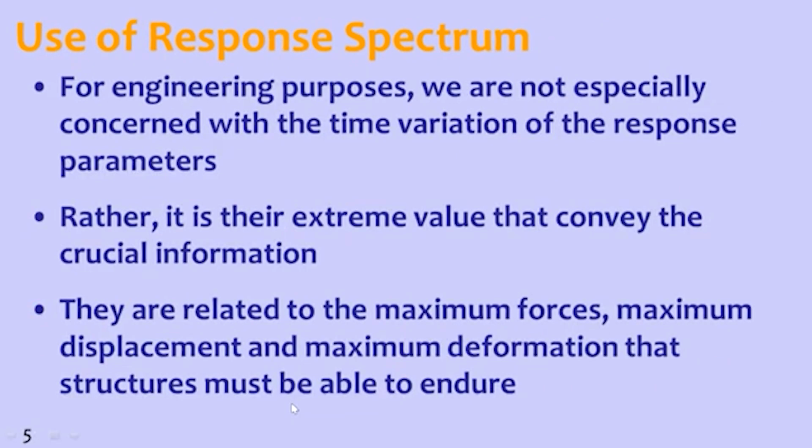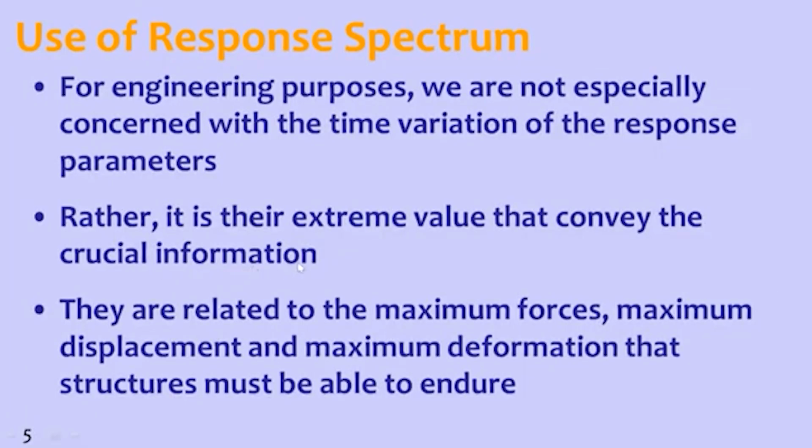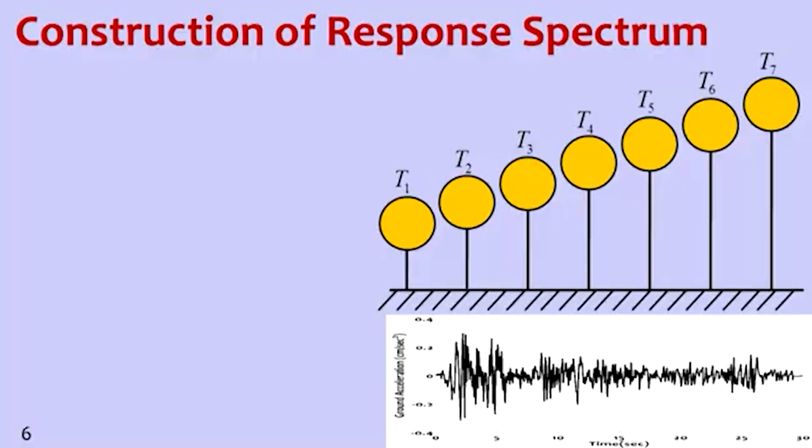Now, uses of response spectrum. For engineering purposes, we are not especially concerned with the time variation of the response parameters. Rather, what we need is the maximum responses. That extreme value conveys the crucial information. They are related to the maximum forces, maximum displacement, and maximum deformation that a structure must be able to endure. So we need maximum values, and hence response spectrum is needed. Now, how do we construct this response spectrum? What we do is we first take a ground motion.